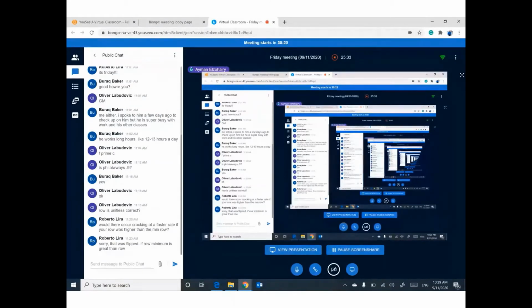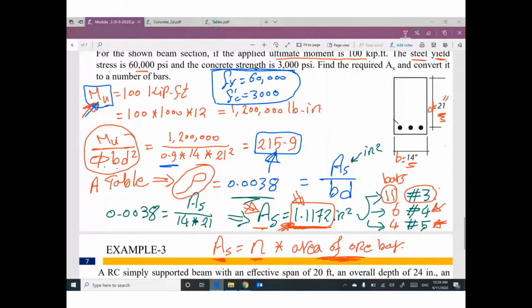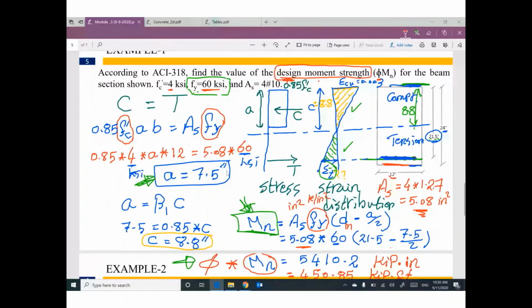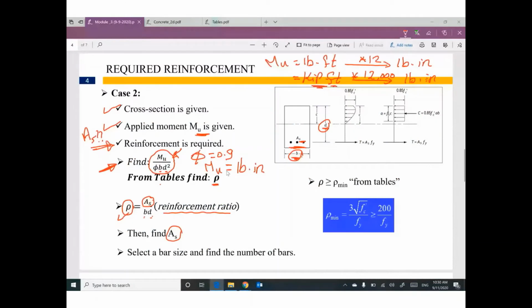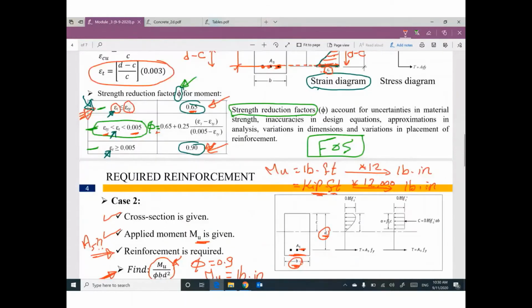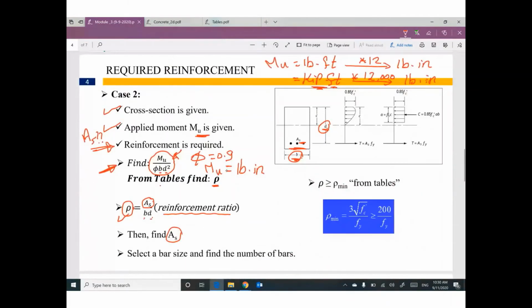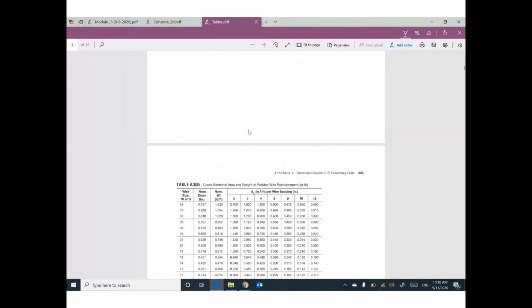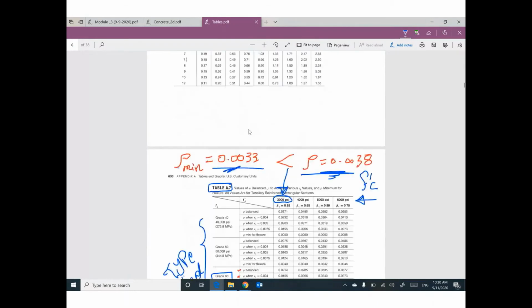Don't worry, Roberto. Okay. Sounds good. So last time we learned it. If everything is given, I can figure out the design bending moment. Now, if the steel reinforcement is missing, the bending moment must be given. So I can figure out the value of area steel and I can check it. Someone will ask me a good question. He didn't ask me this. Okay, looks good.